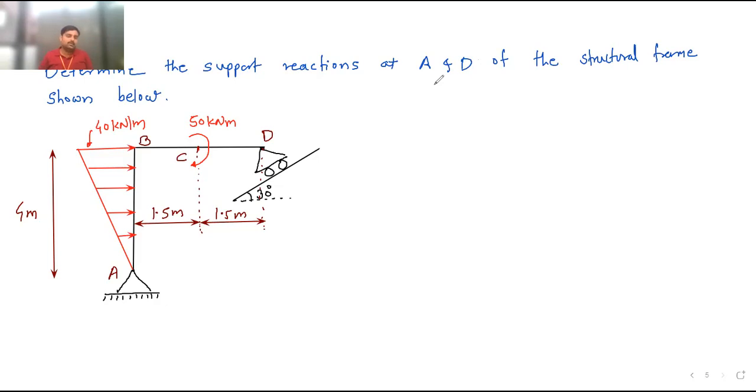Now you think on this. See, we have solved so many problems. Now you think and tell me how to solve it. What should we do first? Start from here. What is the first step when we see a diagram like this? It is a normal beam problem, and it is asked to find the reactions. What is our first step? What do we do first? Draw the line diagram. Okay, that is the free body diagram. First we will draw the free body diagram along with the line diagram. So here I will draw the diagram.